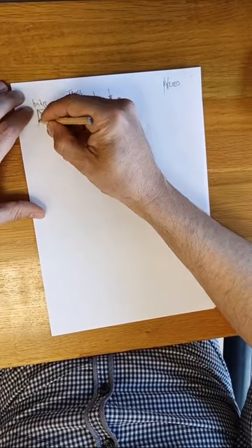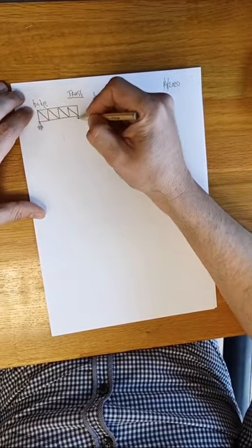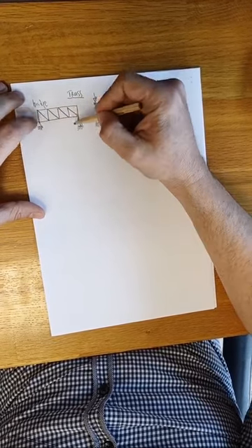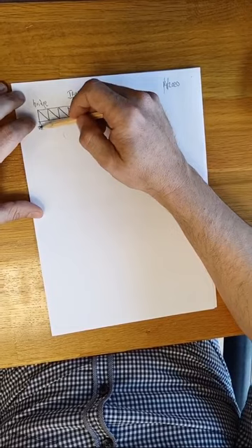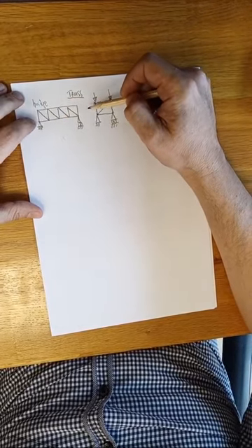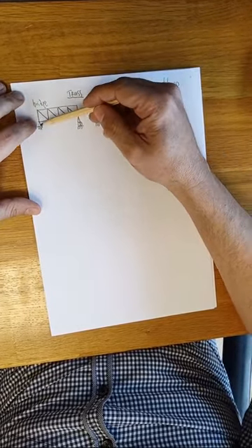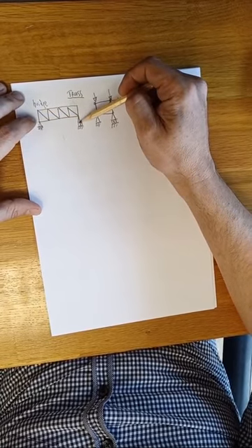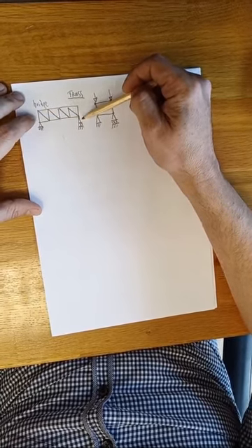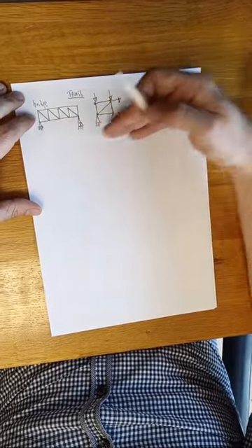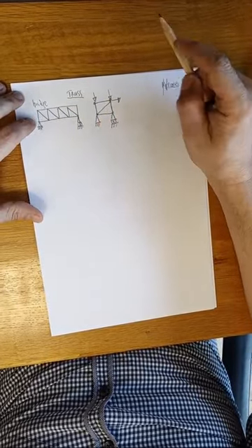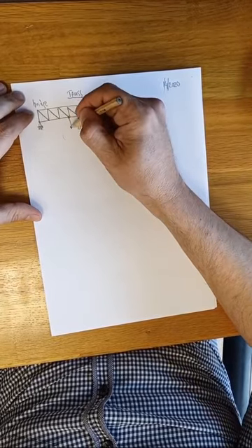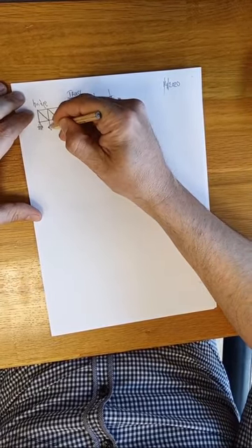Okay, while modeling this truss system, the supports are introduced here and here. Easily we introduce one of them as the simple support, the other one as the roller support, where it is free to move in horizontal direction. This is the easy way of modeling, and we can apply loading like this.